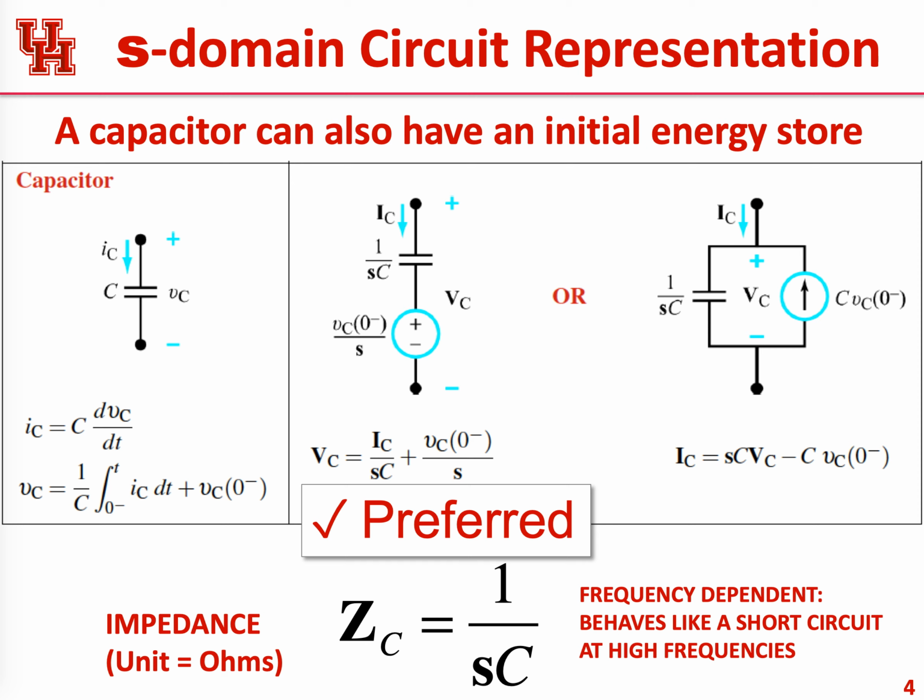So what that's telling us is that the quantity that's analogous to resistance, called the complex impedance of the capacitor, Z of s, is this term 1 over sC. And then there is a voltage in series, equal to this value, that is describing the initial condition. So if I were to describe this in the Laplace domain, I'm going to get a circuit that looks like this.